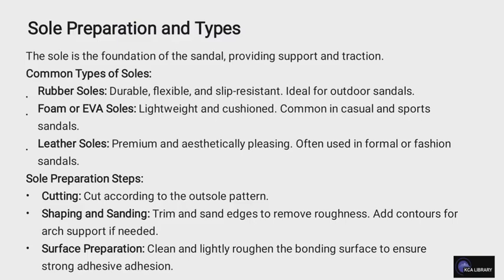Looking at the preparation steps of the sole, the first is cutting, that is, you cut according to the outsole pattern. The next is shaping and sanding, where you trim and sand edges to remove roughness, and then add contours for arch support if needed. The last is surface preparation, where you clean and lightly roughen the bonding surface to ensure strong adhesion.